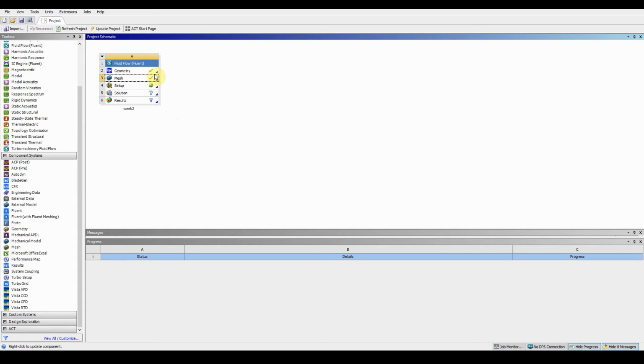If you don't get a green tick, or you get a green tick with a little X next to it, it means there's a problem within your meshing. Mainly it's to do with the name selection. Sometimes you selected one surface and gave it a name selection, then by accident you grabbed that same surface and gave it another name selection. No surface can have two different named boundary conditions, so that's why it always gives you an error.